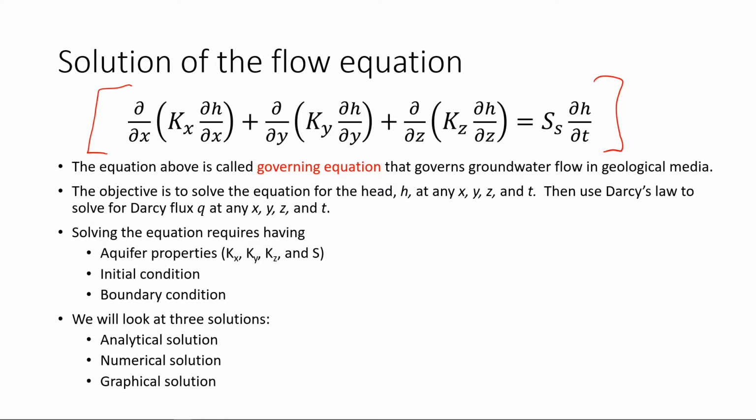So this is the governing equation, but it doesn't matter whether you want to solve this analytically, numerically, or graphically. You need to define the aquifer properties. You need to define these K values, and this is specific storage. So you need to define the aquifer properties regardless.